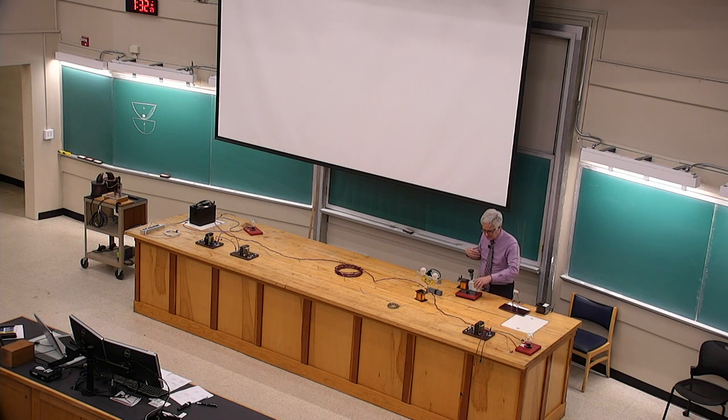What I want to show you is this. This is a step-up transformer. I think I'll stick with this just to show you. The difference here is that, as I showed you on Friday, the energy is going to move from one circuit to the other. Again, we have an isolated secondary circuit. That's the secondary coil. It has many turns of wire, and therefore it experiences any electric fields around this chunk of iron many times, and much work can be done on charges that move with those electric fields.